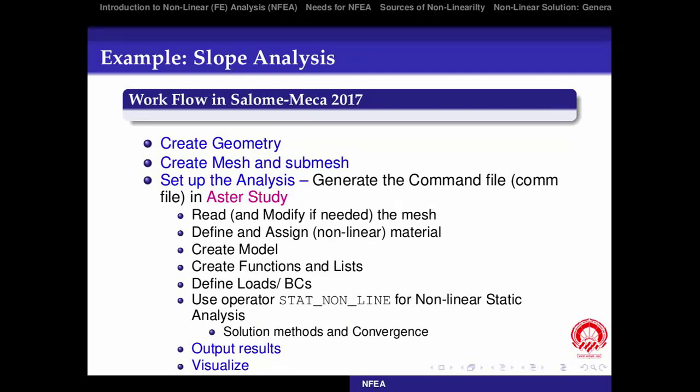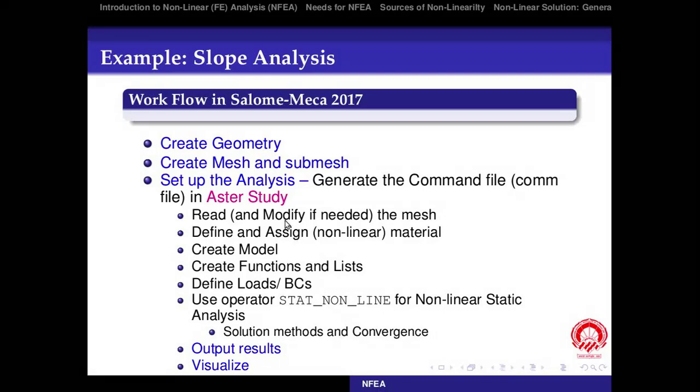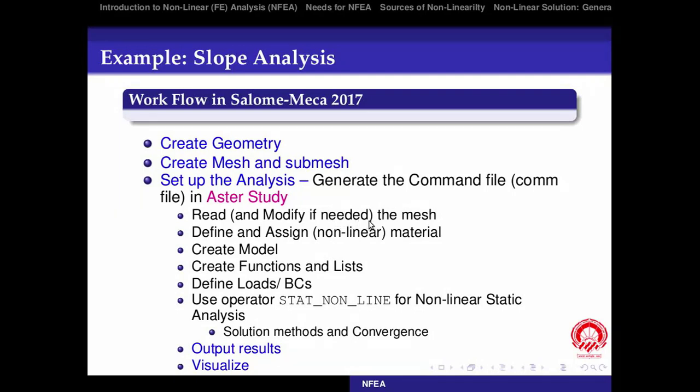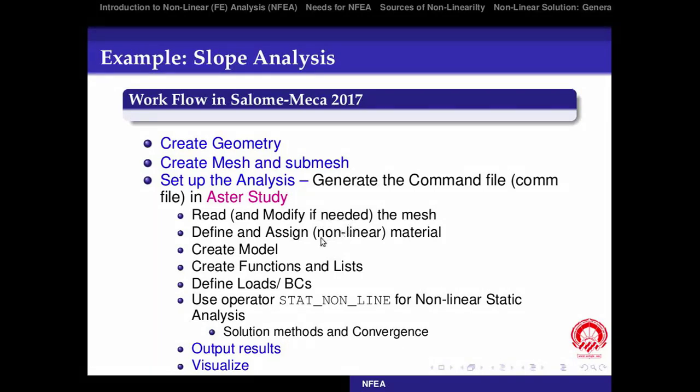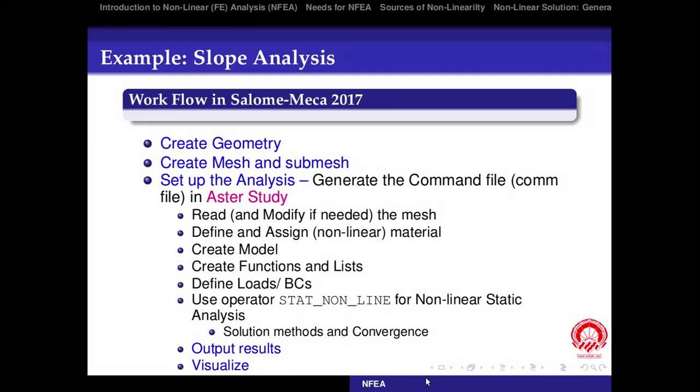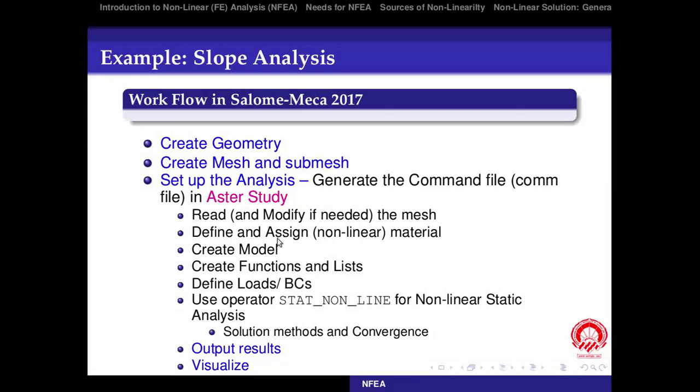What we do in this Aster study is, first we read the mesh, then we modify the mesh if needed. We'll see what are the situations when we may need the modification. Then we define some nonlinear material in this case and assign the material to the finite element model. Well, this is wrongly ordered. First, after reading the mesh, we need to create the model. Then we need to define the material and assign the material to the model.